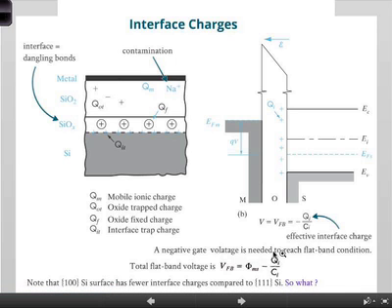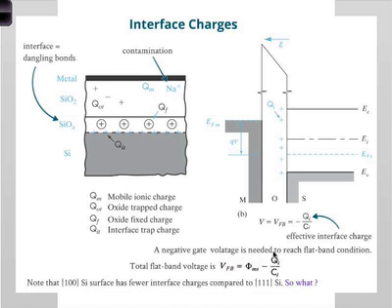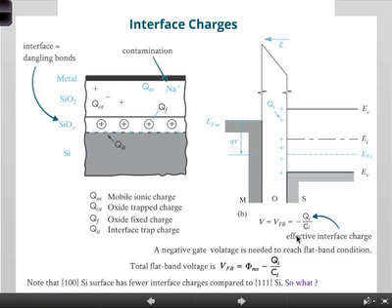Okay? These things, the problem with interface charges is that it's very hard to control them. So you want to minimize them first, because they can be kind of random. Of course, you don't want to have random fluctuations among billions of transistors in your CPU, right? Because it will be impossible to design. Okay? So that's the answer to so what, basically. Okay? Keep that picture in mind.